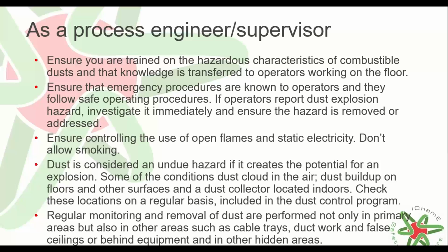Dust is considered an undue hazard if it creates the potential for an explosion, and some of these conditions that may indicate the potential for an explosion are, for example, dust build-up on floors or other surfaces, as we could see in the first case study, and the dust collector located indoors, as we saw in the second case, and many others. Make sure that you check these locations on a regular basis, included in the dust control program.